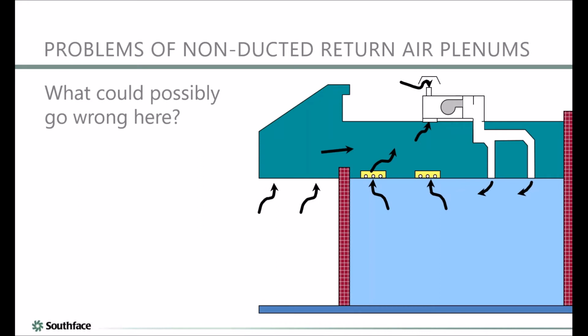It's amazing how common this type of issue is. And it really comes down to this: when you don't have a dedicated or ducted material as a duct, then it often gets violated. Even if it was built perfectly in the very beginning, it still gets violated over time. In this particular car dealership, there were all kinds of leaks at the top, but there was actually a giant hole that had been smashed, because an electrician had come out and replaced the light fixtures out here, and it left a 3x4 opening.